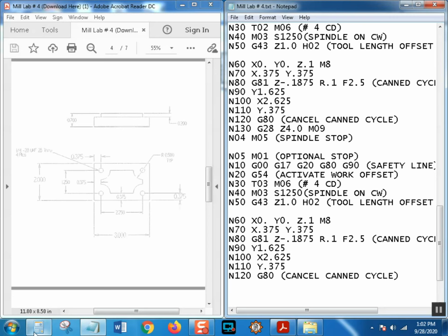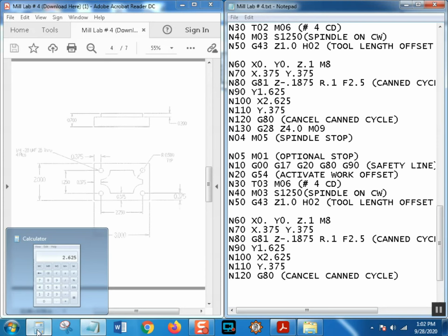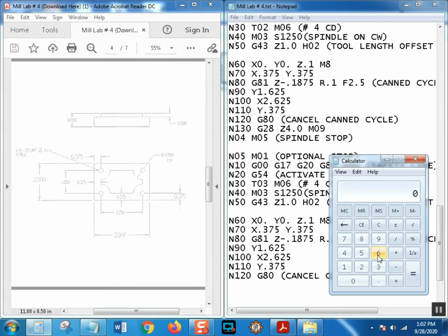Well, I can tell you how to do that real quick. You just take the major diameter minus the pitch. You're going, what? Yeah. So the major diameter is 250 thousandths or a quarter of an inch. Minus, okay, 1 divided by 28. You're going, what? That's pitch expressed as a decimal. Now, like I said, I try to get this thing to do parentheses. It doesn't do it well. So let's try it like this again.